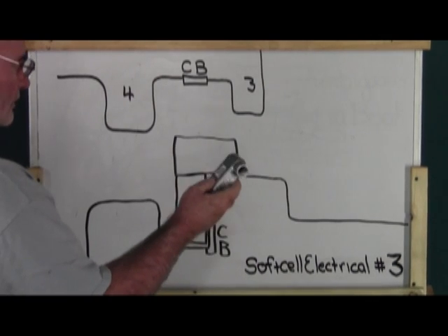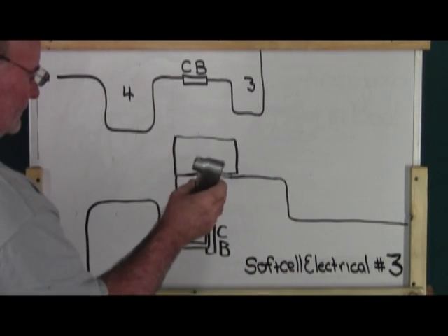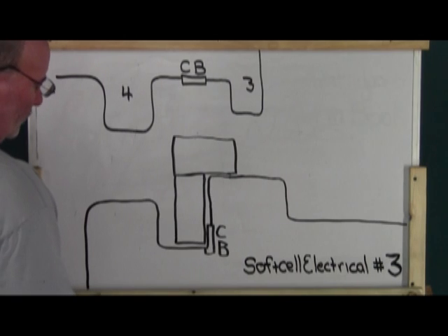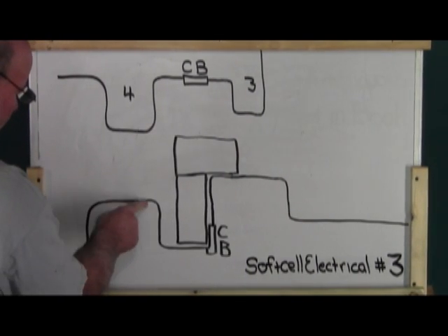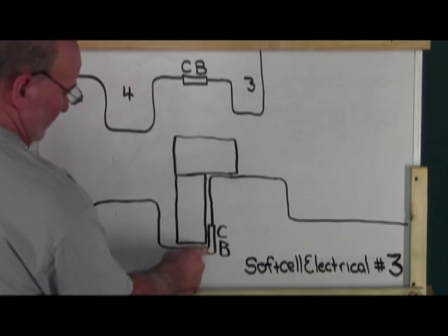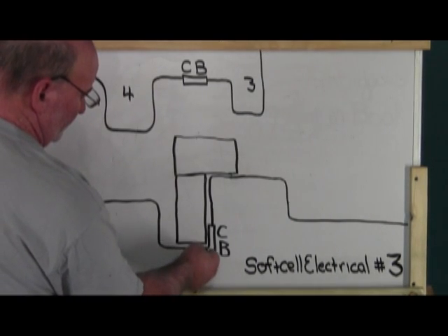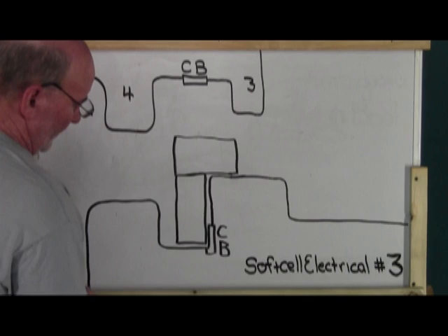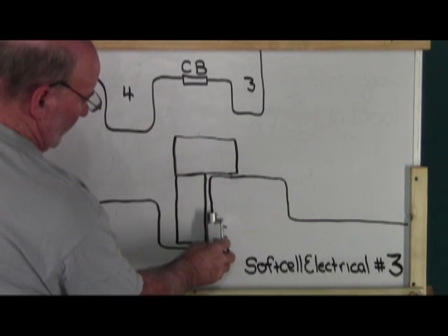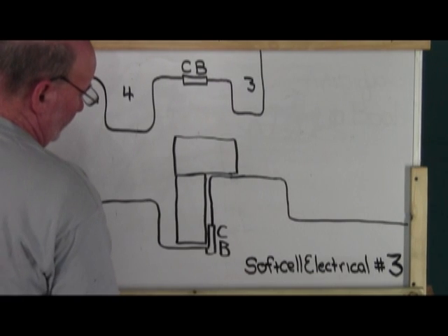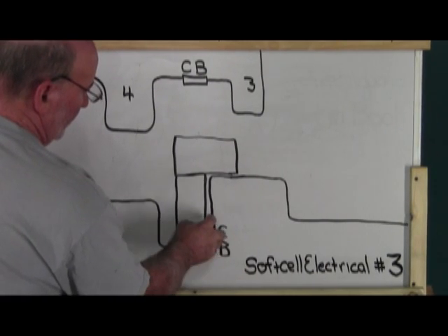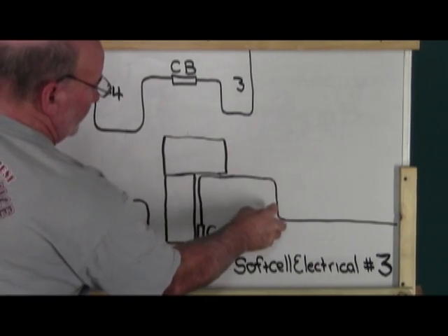On an LB or a side out, these are particularly useful for going around corners. So you have 1, 2, 3 bends, and you can't do a bend around a corner, so you use your conduit body. It gives you access to the wire, and once you get to that, you go with another bend and 3 more.